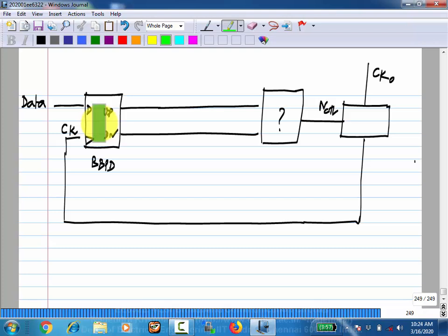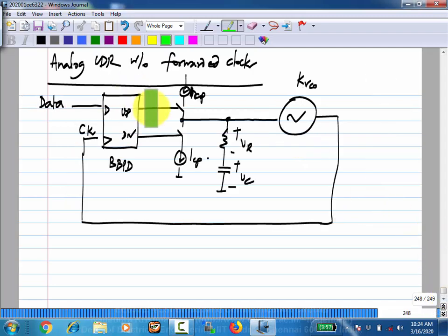Okay, so what should this have? I mean, you can take a hint from this, right? You have up and down here, and the control voltage is over there, and the phase is here, right? And we've already evaluated the incremental model of this and so on. So, the phase of this clock, what happens to it in response to, let's say, a single up pulse? What are the, I mean, there are two components, right? What are they actually? So, what does each of those things do?